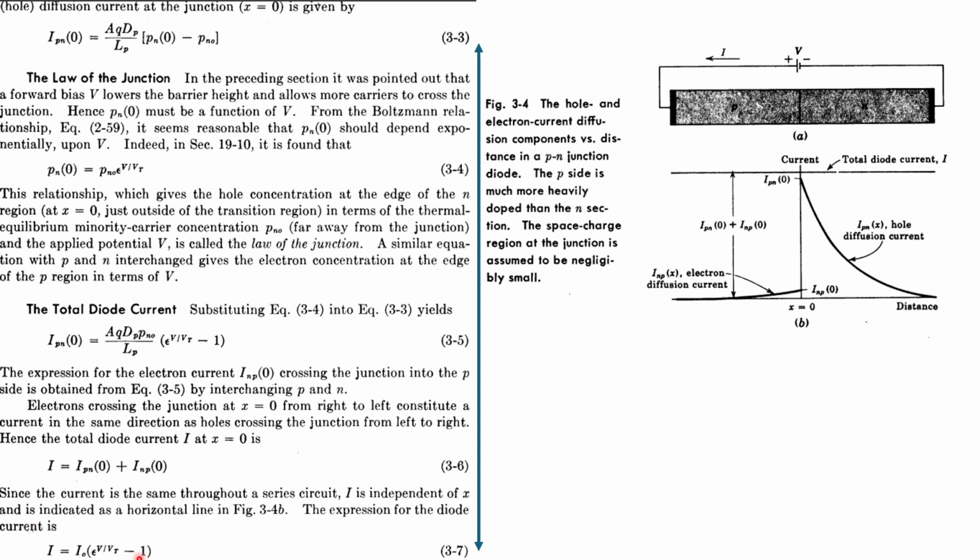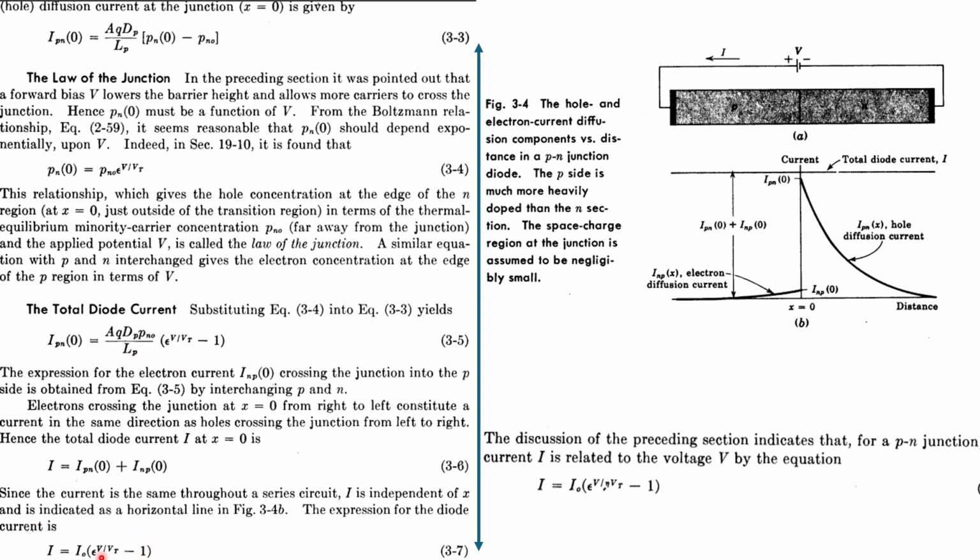So this is the final current equation, and it was further modified later, so here we introduce one eta term: I is equal to I naught times (exponential of V divided by eta V_T minus 1), right? This is the important current equation that you should remember. We will continuously use this current equation to find the amount of current inside your diode.